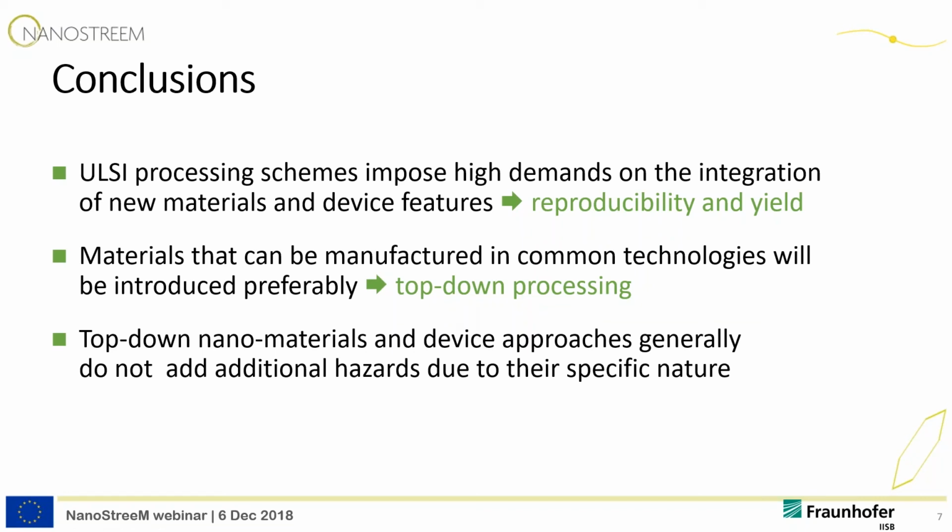The ULSI processing schemes impose very high demands on the integration of new materials and device features in detail, especially reproducibility and yield are the predominant requirements that have to be fulfilled for each production environment. And with the very bad alignment capabilities you have with bottom-up grown materials that are dispersed and spin coated or transferred by any mechanical technique, people always suffer from difficulties and from high defect rates and from bad yield.